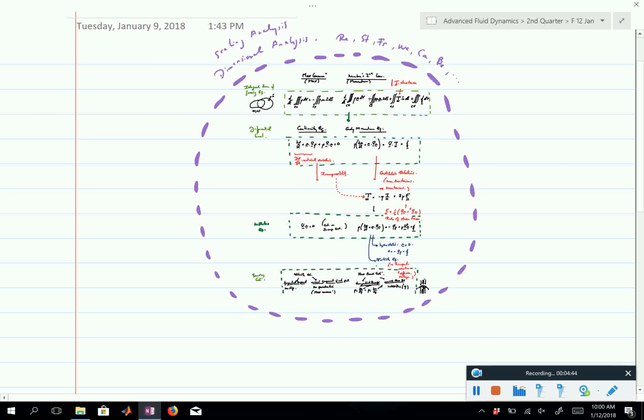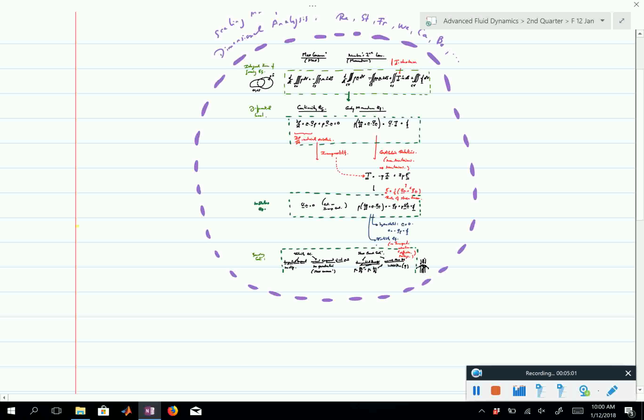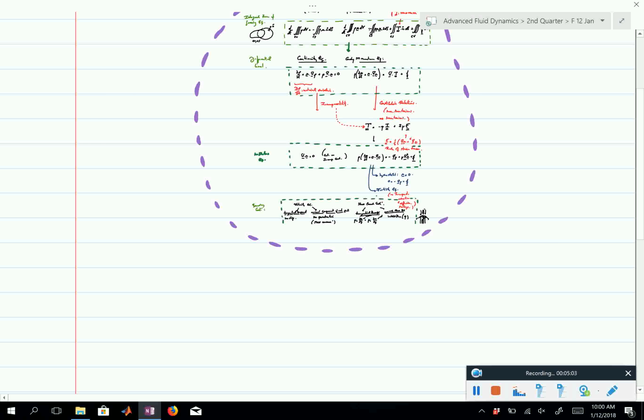So let's compute the Weber number. This is what I get. This is high. I can neglect the effect of surface tension. Right? Sometimes it will help you to be able to compute those numbers because it allows you to make the right assumptions in the problem. Okay, dimensional analysis. And then the important one, of course, I'm going to put here on the bottom, is the Reynolds number.